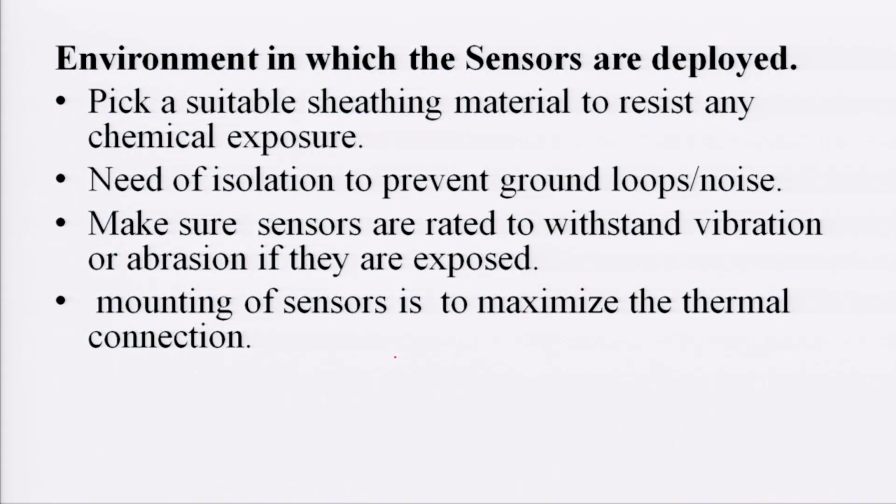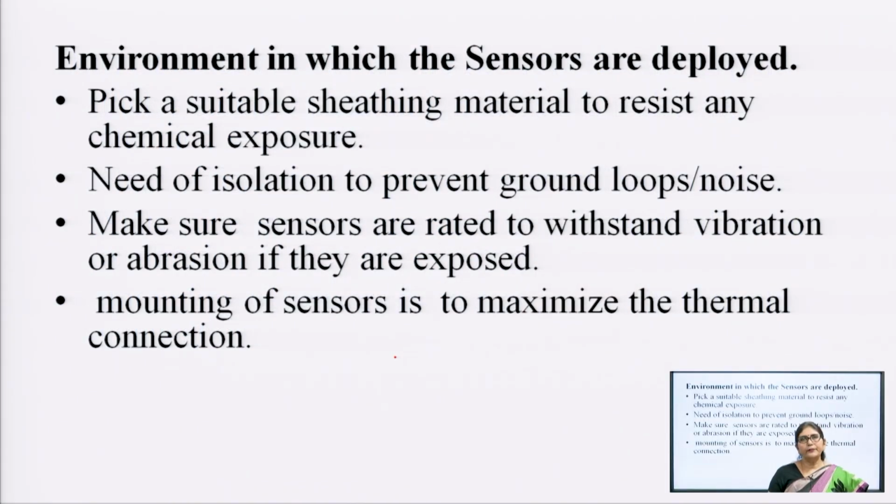Next, make sure sensors are rated to withstand vibration and abrasion if they are exposed. It should withstand vibration if it is used at a place where there is vibration, because in the mechanical industry the sensor is placed at one place and the vibration is at another place, so its reading should not be affected by the vibration. Then mounting of the sensor is to maximize the thermal connection, so mounting should also be taken care of.